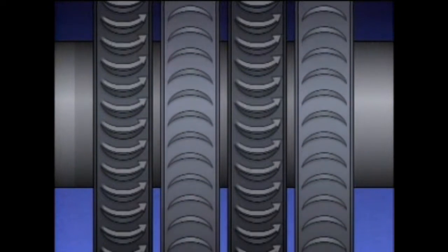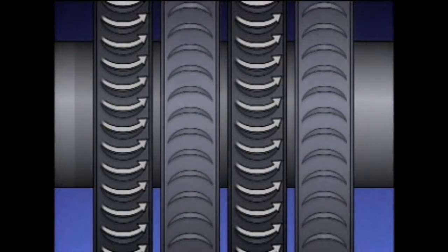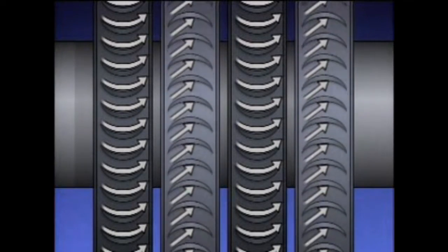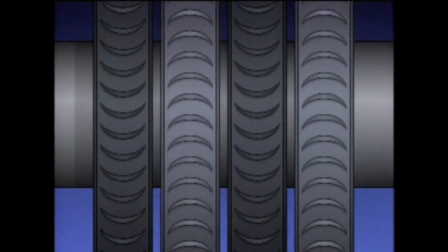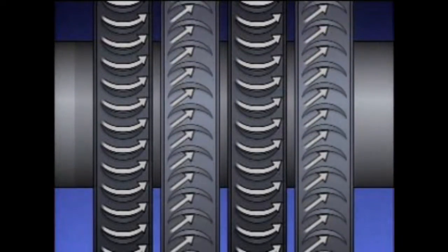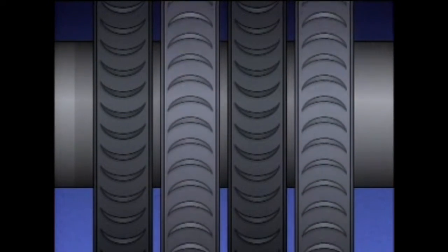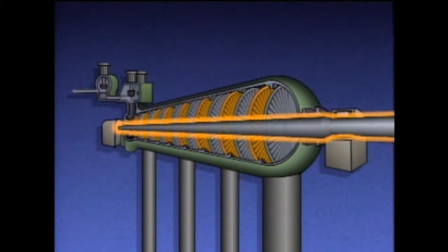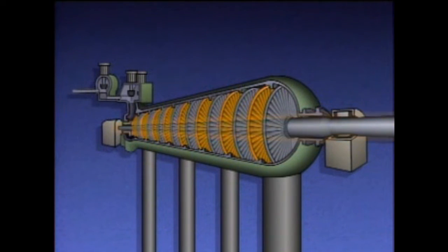Their function is to direct the flow of steam leaving one set of rotating blades into the next set of rotating blades. Wheels, on the other hand, are moving parts. They are designed to turn as the steam flow passes through their rotating blades. The rotation of the wheels turns the shaft and the generator. Diaphragms are sealed where the shaft passes through them to minimize steam leaking through this opening and bypassing the diaphragms.